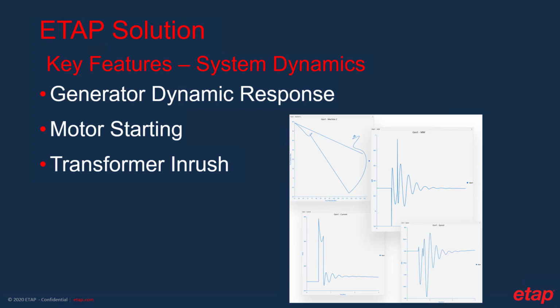One major feature that is unique to the ETAP eOTS solution is the system dynamic support. This is because the transient stability engine is utilized within the OTS simulator. This gives the trainees a very realistic window into how the system actually behaves. For instance, when a large transformer is energized, the associated inrush can be seen in the operator screens. This is something that you can't really see in other non-model-based OTS solutions.